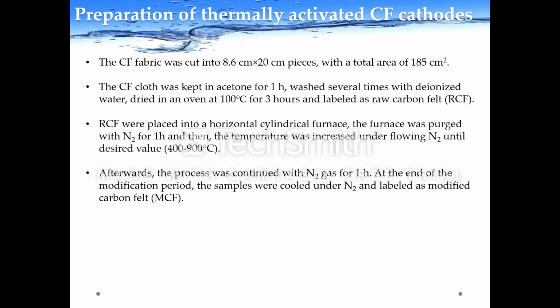After that, we placed this raw carbon felt into a furnace, and the furnace was purged with nitrogen. Then we increased the temperature under flowing nitrogen up to the desired value. Afterwards, the process was continued with nitrogen gas for 1 hour. Then the samples were cooled.